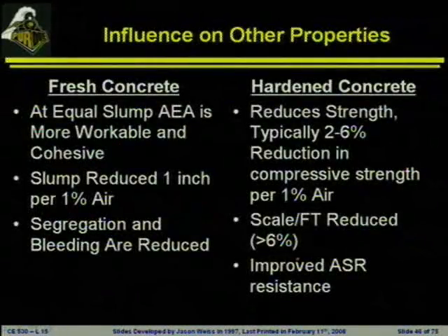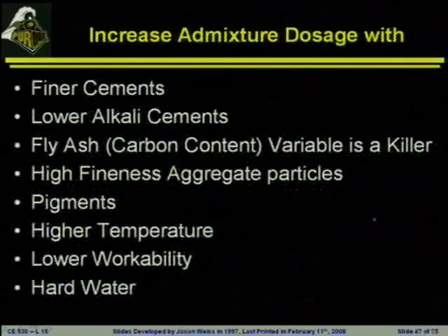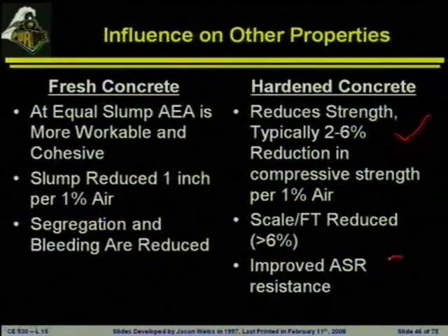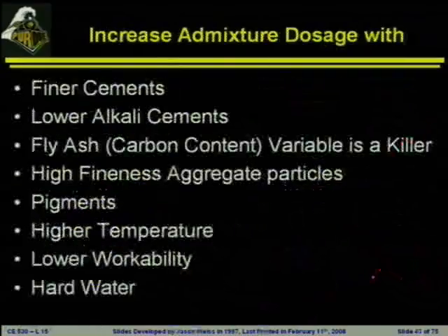I'm not going to spend lots and lots of time talking about some of these other issues. We talked a little bit about the reduction in strength. As I mentioned when we were talking about ASR, here you'll see people saying that ASR can be reduced by adding a little bit of air to the system. All you're doing is creating a little bit extra space for that gel to be forming.